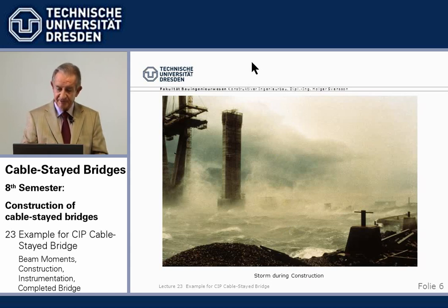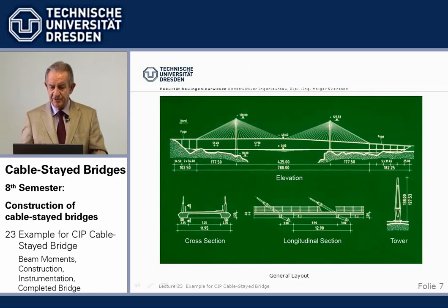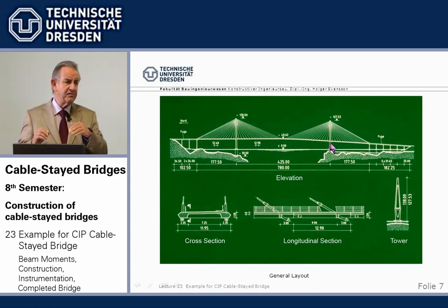That was there. Now, the bridge itself, due to the geology I showed you, had a minimum length of 425 meters. We wanted, again, because of the strong winds, a beam as low as possible, so we have little wind resistance or wind action. So we chose 1.2 meters, which for a 425 meter main span gives a slenderness of 1 in 354.